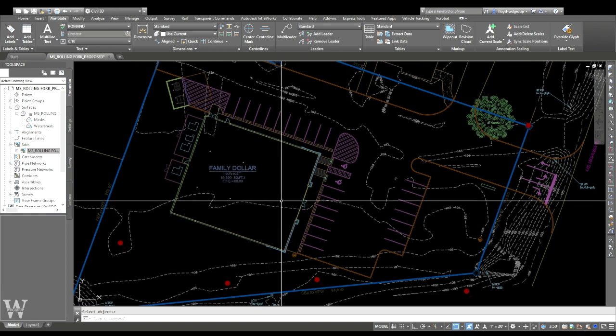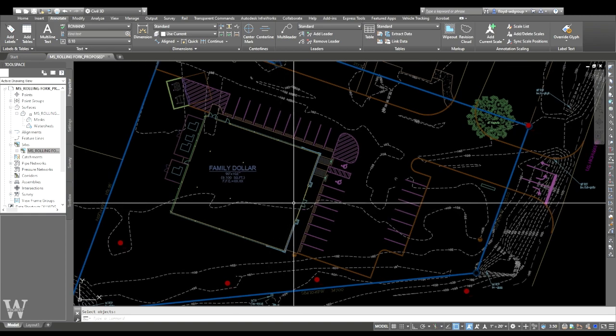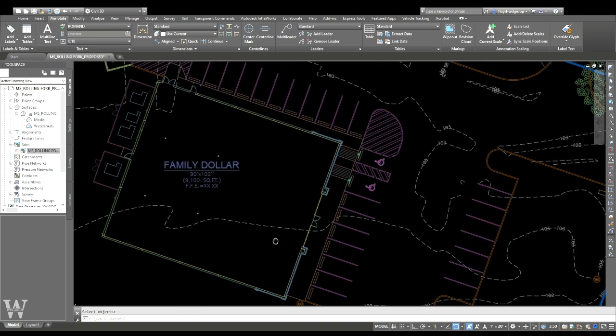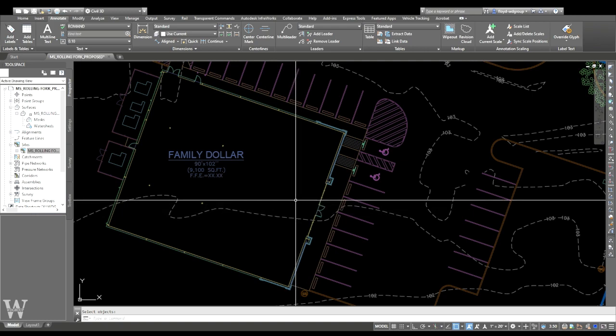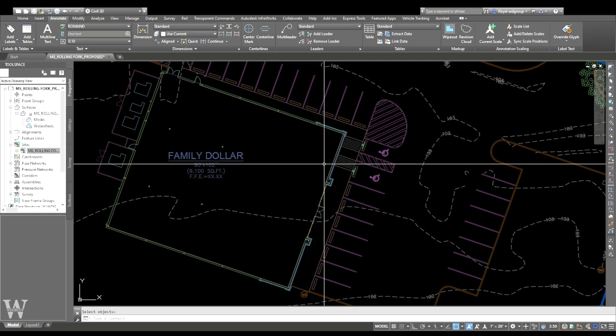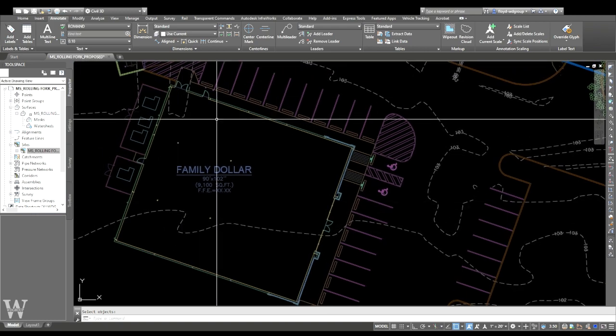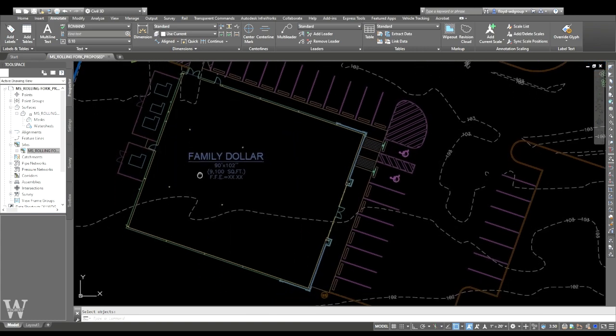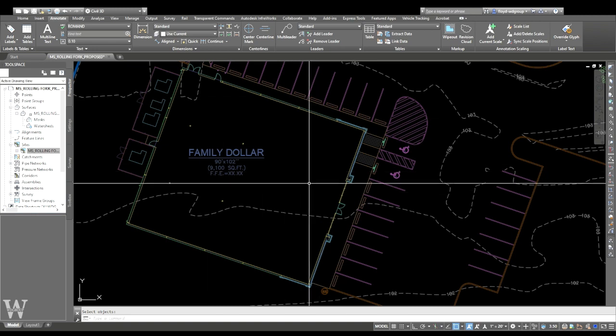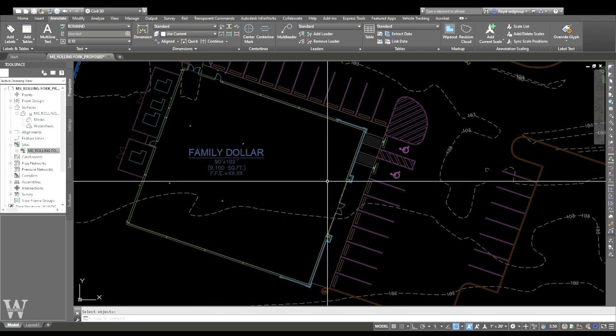Okay, so what is the process? As I've discussed pretty in depth in the video before on this, what I like to do is around the building with all the sidewalks and the HVAC pads and such, I'm going to draw feature lines. That's the way we grade. I can't find a better way to do it.